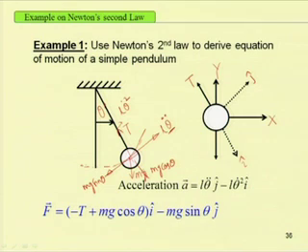So, as T will be equal to mg cos theta, the resulting force acting on the system equals mg sin theta, and the inertia force is also acting on the system. So, the total external force on the system, as I am taking a coordinate system i in this direction, will be minus T plus mg cos theta i, minus mg sin theta j.